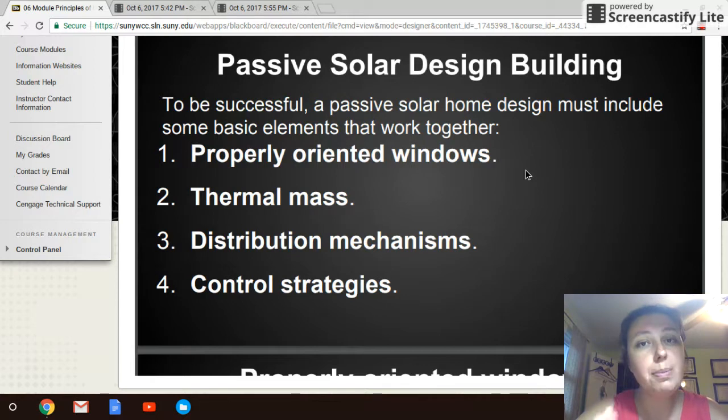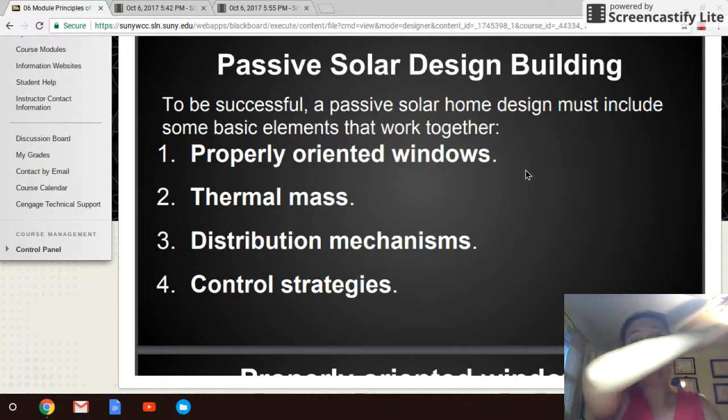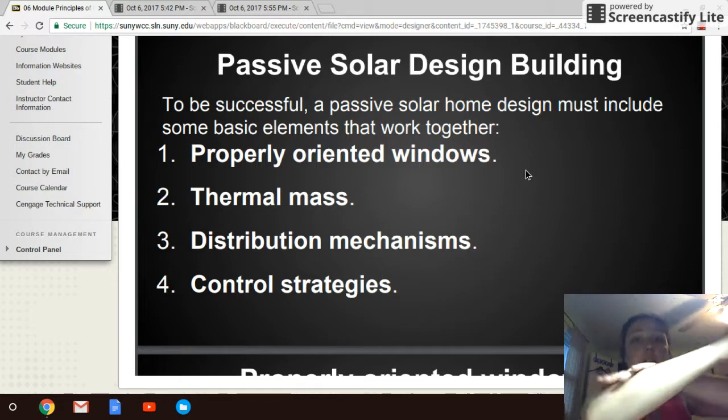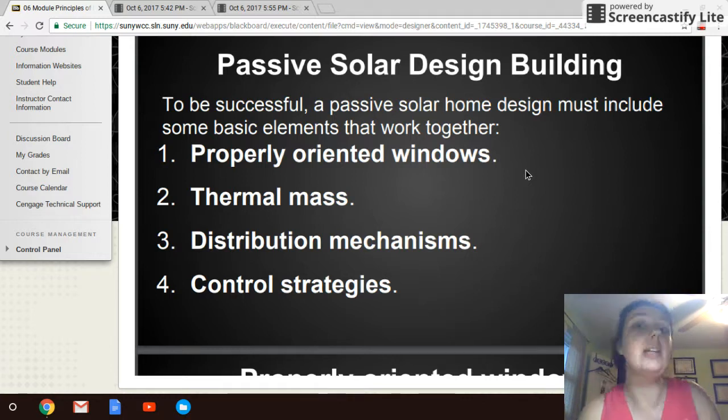so that you maximize sunlight in the winter, so that the lips or overhangs or angling of the roof structure allows sunlight to enter through the winter when it's low in the sky, right? So my angle of my home and the sunlight can get right in. And then that angle will block that sun from getting in when the sun is high in the sky up here, it won't get past the roof structure. So passive solar home design is maximizing sunlight in my cold months, winter, and minimizing sunlight in my warm months, my summers, right? So I'm getting things that are appropriately angled and built to the proper structure.